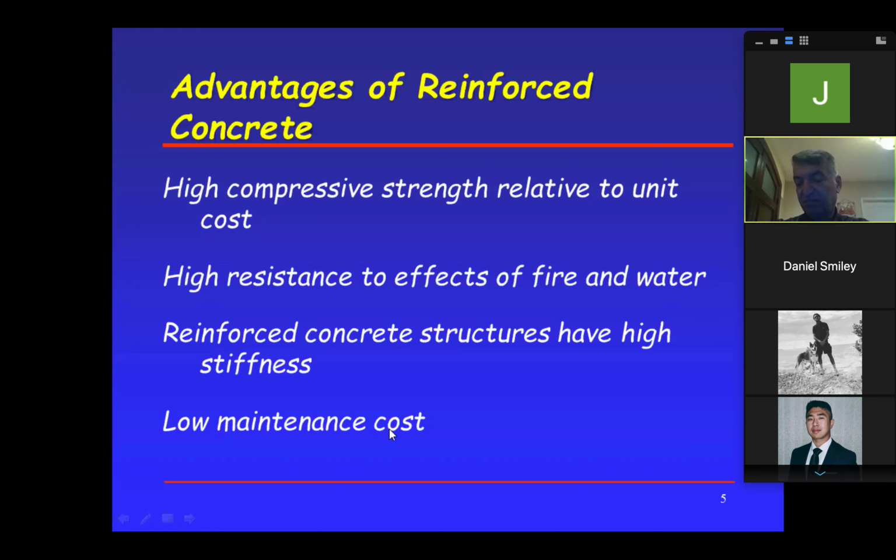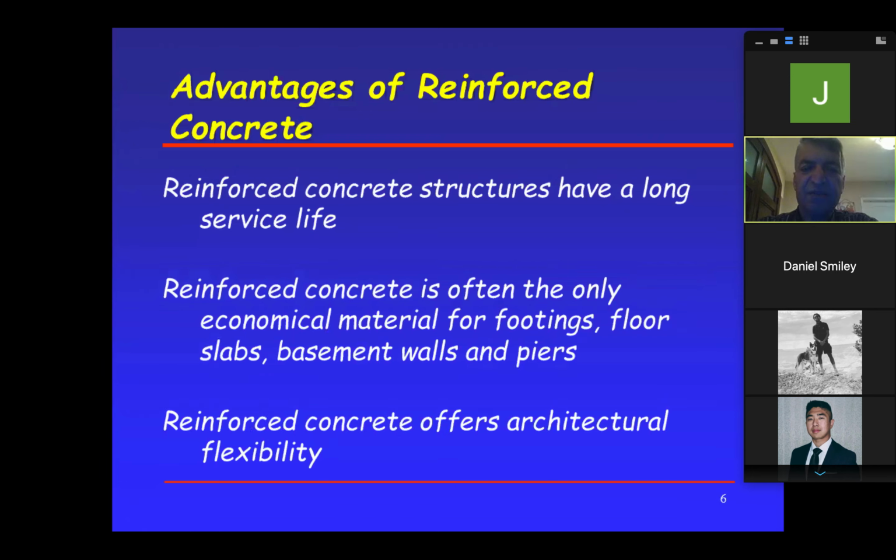Low maintenance cost. You put it in, you forget about it. Concrete doesn't need any maintenance except if it starts to crack and all that, and we will talk about that. So very low maintenance structure. Where wood, you have to paint it, even steel, you have to paint every so often and all that. Okay, more advantages. Reinforced concrete structures have a long service life. If a building is done right, it can serve you 100 years with no problem. No problem at all. 50 is definitely a given, no problem. Okay, so very, very long service.